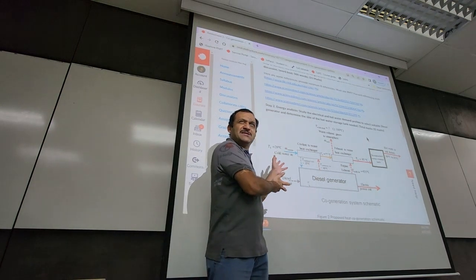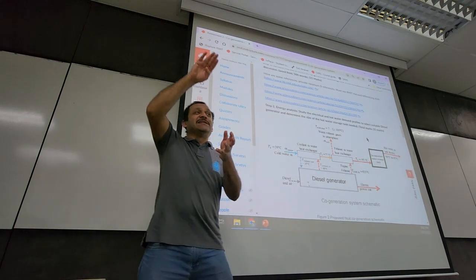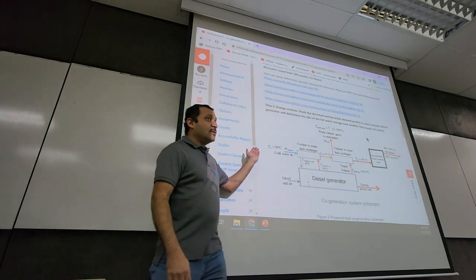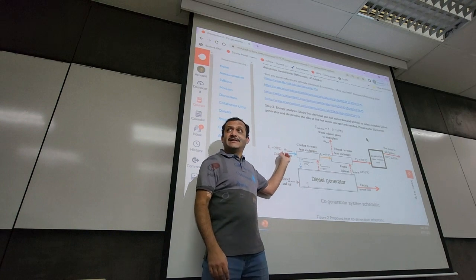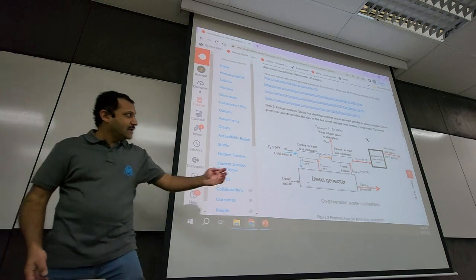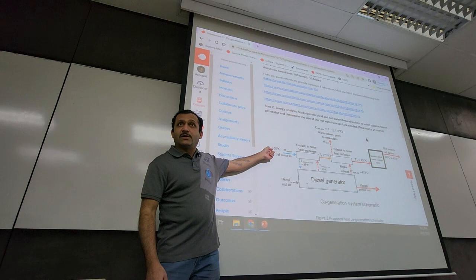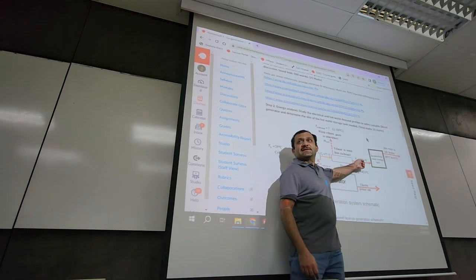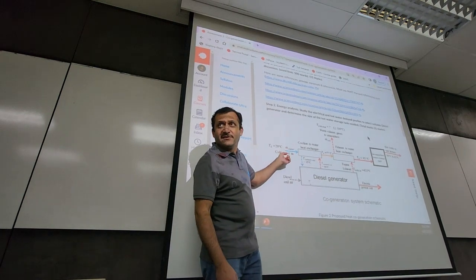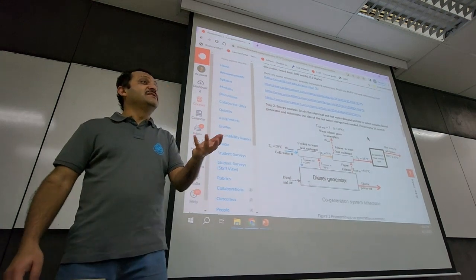But for assignment, academic purpose, what I've done is said, okay, average is this much for 1 hour. But the next hour it increases. The following hour it decreases. Again increases. So what you need to do, you're getting that water from some local water source, local bore, which is coming in at 20 degrees Celsius. You want to heat up that water to 85 degrees Celsius. Okay? So if mass flow rate is given and you know the temperature difference, would you be able to find how much amount of thermal energy you need to heat it up?